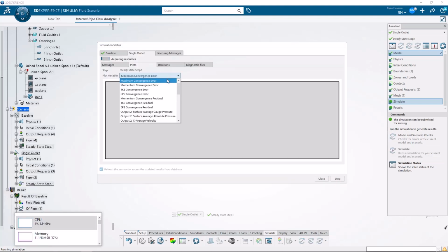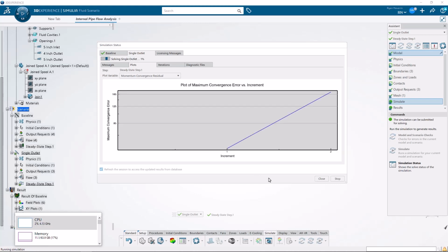So we'll go ahead and click OK. There will be a slight delay for the cloud solution to begin based on your internet upload speed, since it does need to upload the files to the cloud, and then also the time to provision an instance. So we're just going to skip over that delay here. It was maybe a minute or two. I do think it makes sense to maybe make sure your initial study can run first locally, and then when you want to do more refined runs, longer runs, variations, send those off to the cloud.